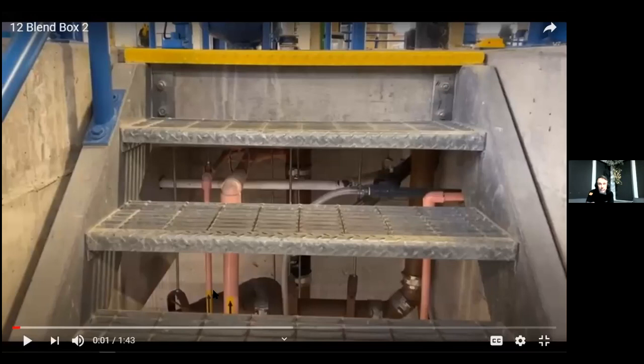Perfect. Okay, so what you're going to see here, and unfortunately I should have showed this video first. At the top of these stairs, we're going to look at a rapid mix chamber, right? And ours are fairly big. Keep in mind today when I did this video, we're probably producing in the neighborhood of 15 to 20 million liters a day. That was the flow coming through the plant. What you're going to see here is a rapid mix tank. Chemicals are added just before this tank or into this tank. There's some mixers. You'll see 2 brown or blue mixers. They are mixing. That's your rapid or flash mix.